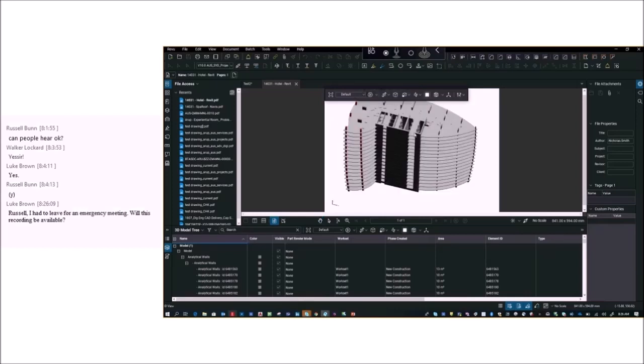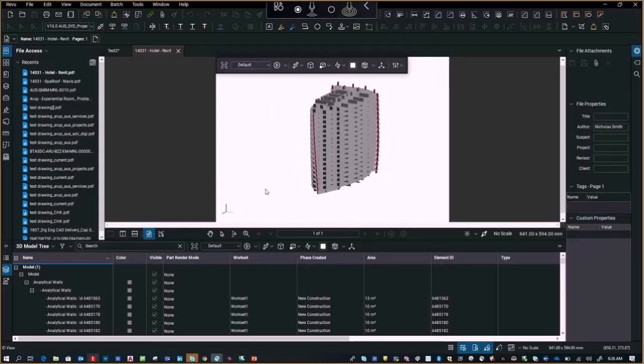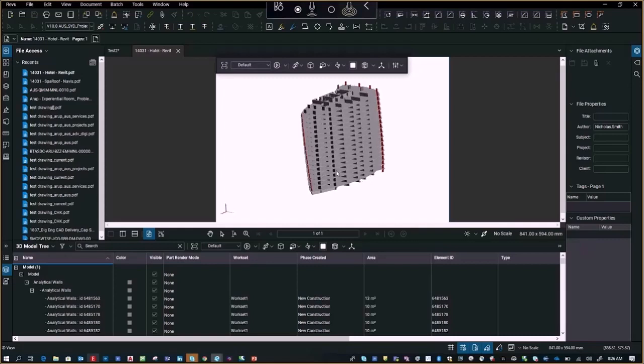It exists in Bluebeam, or that you can actually see that data. For me, that would be isolating elements, and they're not heavy either. If I need to know cable routes, if I'm looking for a new cable route, I can see that much clearer than trying to visualize 10 drawings in my brain. I can see, oh, maybe we can go down there, and done.